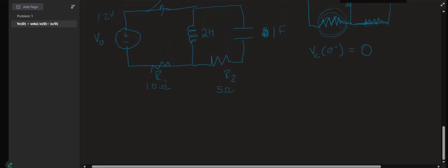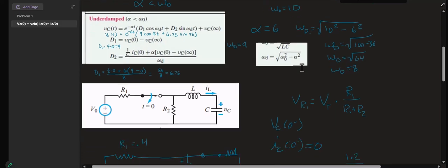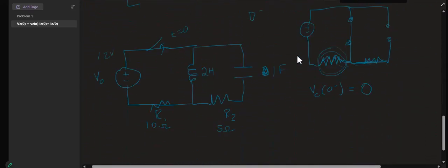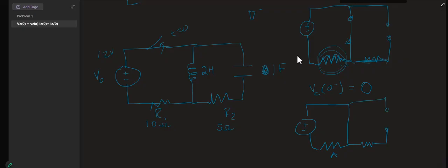I don't get that. It's not the same exact resistor. The resistor from before was in a different place. Like I'm saying in that one example, we're saying it's not in parallel because there's a resistor between the voltage source and the capacitor where it's at, right? It's this resistor that makes it not in parallel. This resistor we don't care about, because there's no current through this resistor. I see. All right, I understand now.